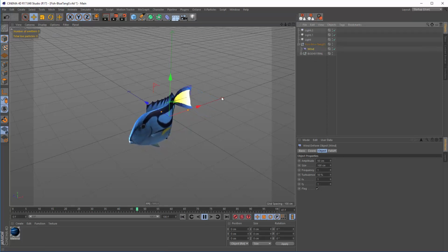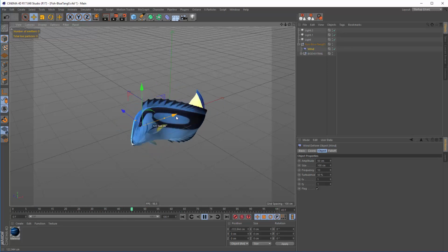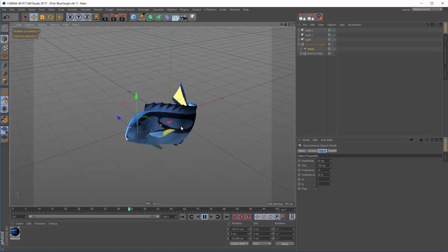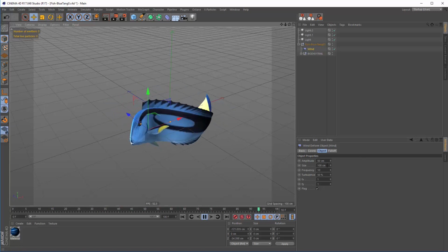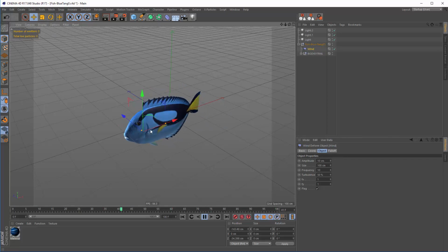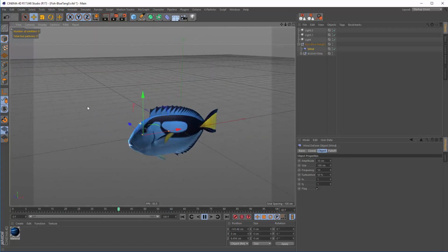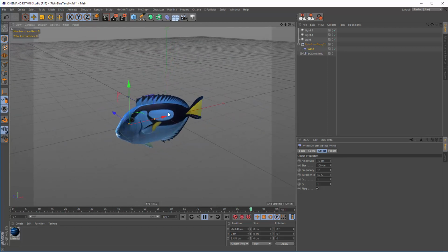And you see that it's acting kind of a fish movement here. So let's change the frequencies to like a 10, and move around this wind modifier. And here you can decrease the amplitude to like 10 as well. All right. Let's put that directly on the head. All right, now we have our swimming fish.